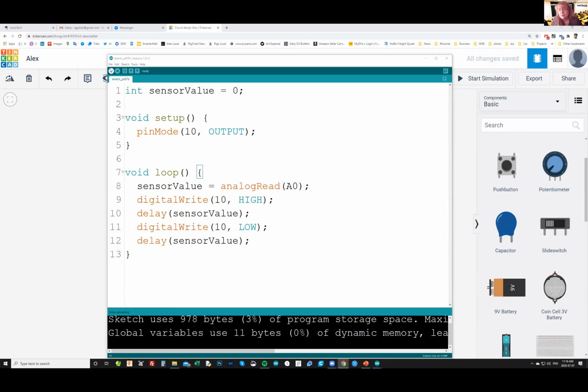Well, after you've done the code, verify is just to troubleshoot if your code makes sense from a syntax point of view, so there are no errors. You can do that, but upload is not going to work until you push it into your Arduino. When you click the arrow to upload it, it technically verifies it first anyway, so you don't actually have to click verify. Verify is only if you're working on the code without an Arduino, if you don't want to upload it. If you want to upload it, you can just click the arrow. So what happens, guys, when you click the upload button, this code gets translated into machine language, into zeros and ones, that is then pushed to Arduino. So verify does a high level compilation just to see if that process is actually doable, right?